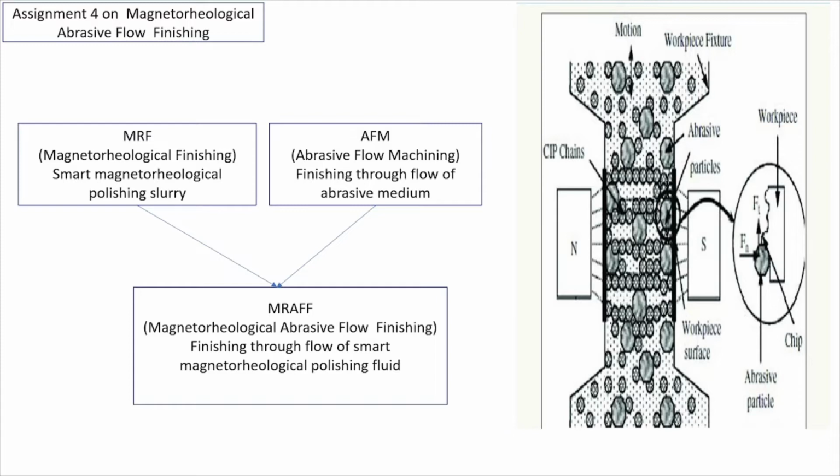The magnetorheological fluid, with magnetic particles, polishing agents and water, is applied to the wheel via the nozzle, and below the wheel surface a magnet generates the magnetic field.